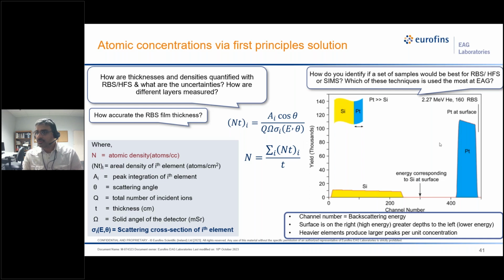Another important thing to know: to calculate accurate thickness, we need the density of the film, or vice versa. To calculate the density, we need an accurate thickness from another technique such as cross-section TEM or cross-section SEM. So in summary, our thickness values are very approximate. They are only as accurate as the density we assume. Another important thing to note is we are obtaining areal density from first principles. We are not using calibrations, and we are not sputtering it out.